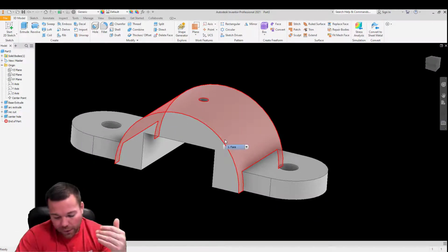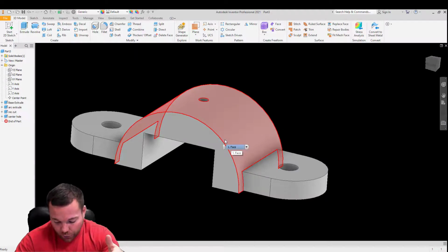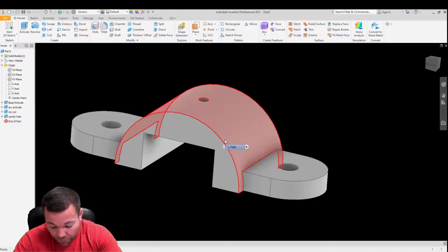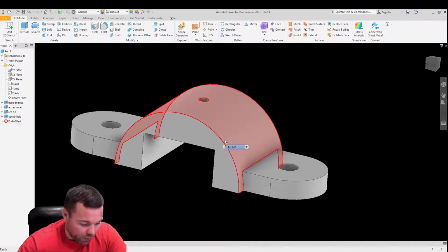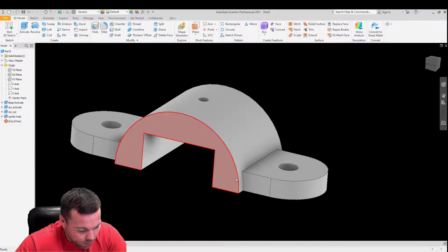All right, so now let's say we have a design change here. So in this next page, it looks like we're taking that rectangular cut and we're actually changing that over to what appears to be a 1.75 diameter. So now we have a radius in there. So let's see what they want us to do here. With Autodesk Inventor, we can take several different approaches. To accomplish this modification, we create a new model, change the shape of the existing cut by using the redefine command, perform feature suppression,